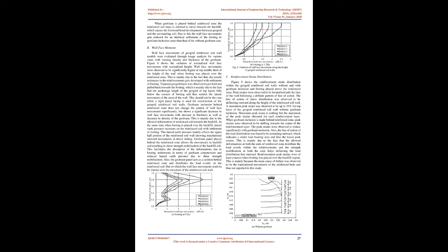Polythene strips were placed such that they move along with the soil during the test and no boundary friction occurs during the test. To ensure firm foundation conditions and that the failure does not pass through the foundation layer, sand with relative density 85% was placed for the bottom foundation layer of 30 mm thickness. Reinforced fill and backfill were placed at a relative density of 55% consistently with the help of the sand pluviation technique for all the tests performed.